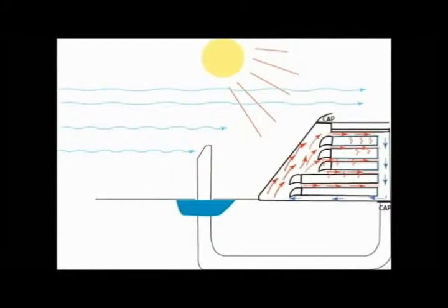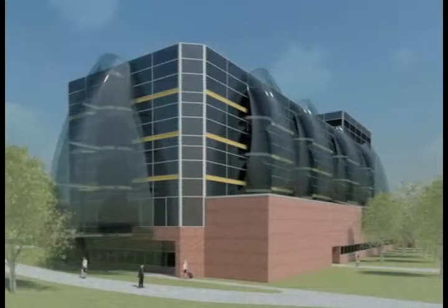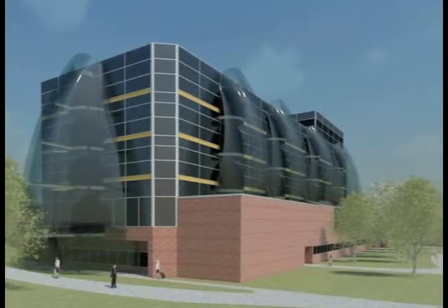During the heating season, the unit vent and ground tunnel are capped, and the system becomes a closed loop. As heat and pressure build up within the controller, the heat is pushed into the floor pipes, releasing heat. As the air moves to the other side, it loses heat, causing it to cool and drop down, and the cycle begins anew.